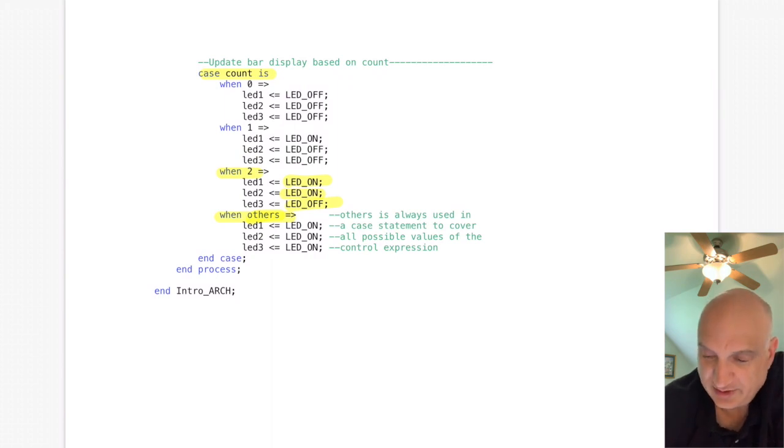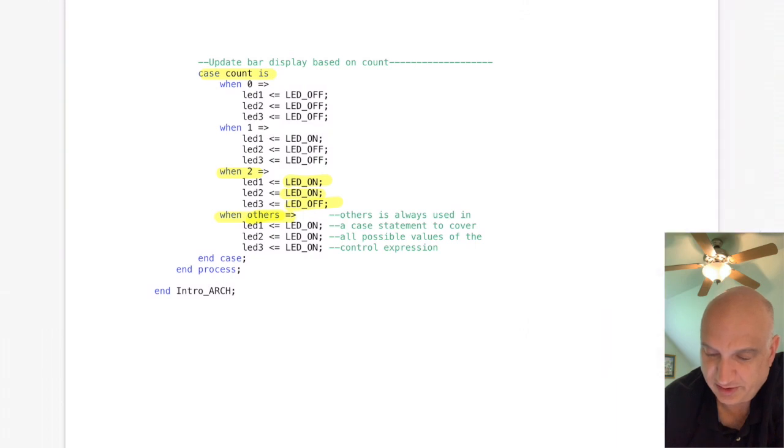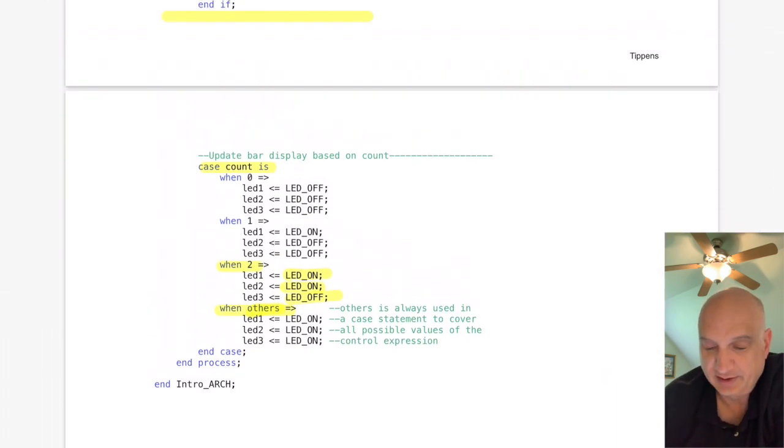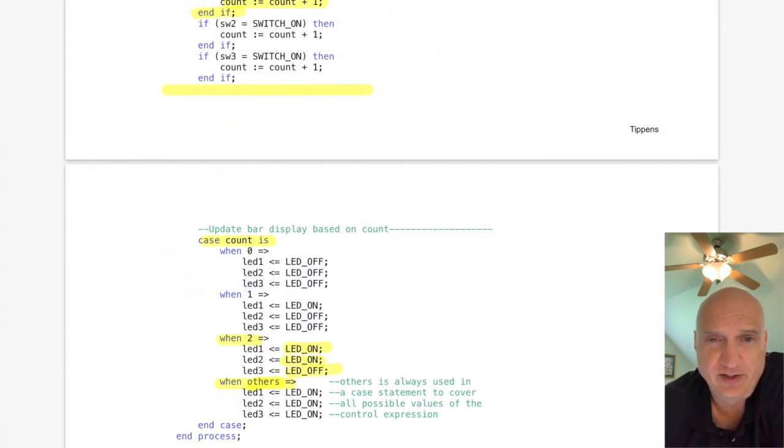The truth is, and this is surprising to a lot of people until we talk a little bit later about what's happening during synthesis, this is actually no more inefficient than those 3 lines of Boolean. In fact, this code may likely be easier to maintain and more efficient than the other data flow code. The reason I say that is when we write Boolean expressions, we are telling it how to wire the hardware. We're not asking it to do any optimization.